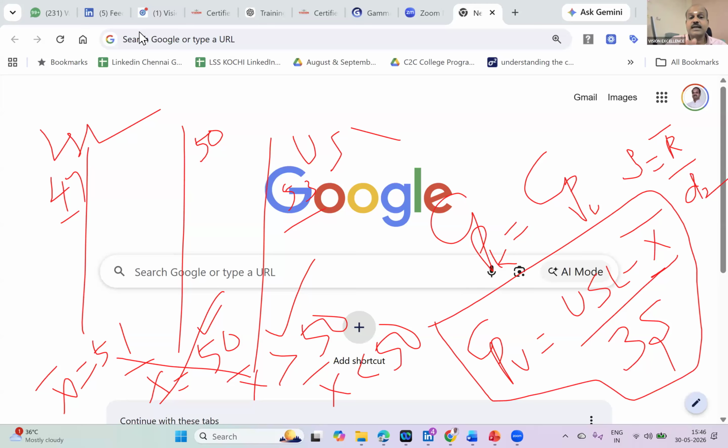This is called within standard deviation, variation within the subgroup, variation within your sample set. You have taken a set of 10 samples. There could be a variation within the 10. That is called within variation. How to quantify that? R bar by D2. So use that formula. CP upper is obtained and CP upper will be equal to CPK.